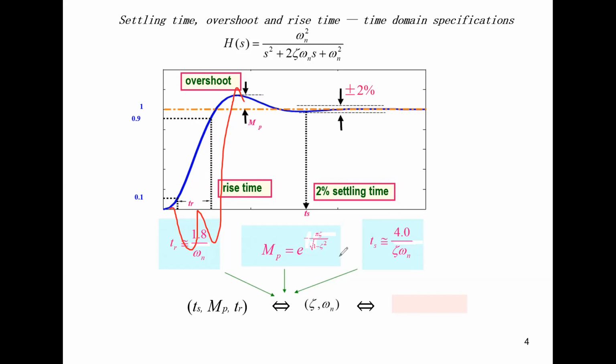Sometimes, if you know the output is here and probably goes over there, negative, of course you will say that the overshoot has to be below that negative value. The magnitude, we're talking about this one. Is that clear? That is how you compute the overshoot for your mini project. Your mini project system is very complex, a 6-order system, so the transient behavior will look very strange compared to this standard 2nd-order system.